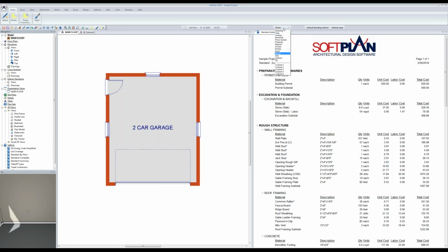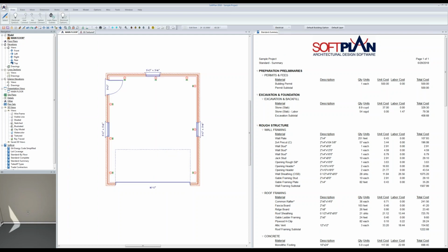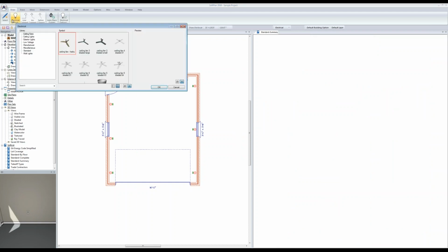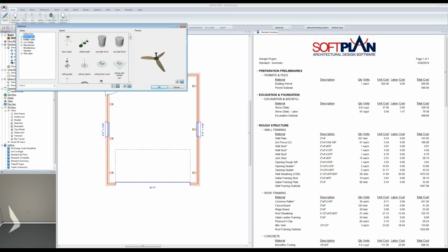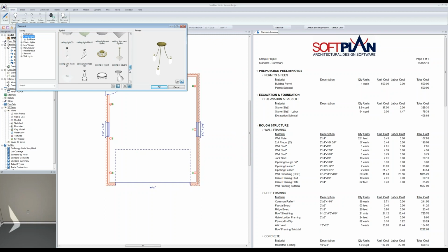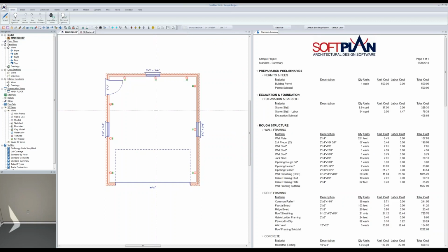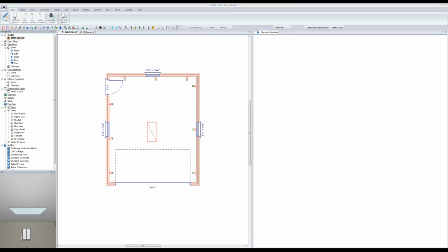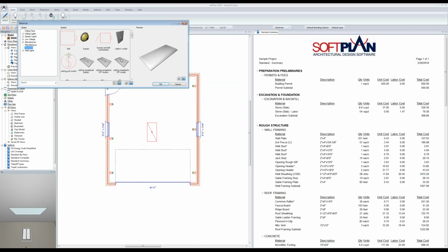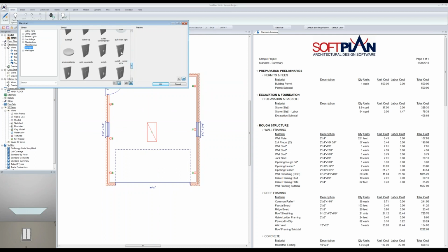So as I was discussing, if it was the electrical, you needed to add a ceiling light to it. We can switch the drawing to electrical mode. Electrical symbols, ceiling lights. Should be a fluorescent light down here, might be appropriate for a garage, so add a fluorescent ceiling light and quickly add it into the room. You can add other options, a switch, which would be under a standard library. Add that to the door.